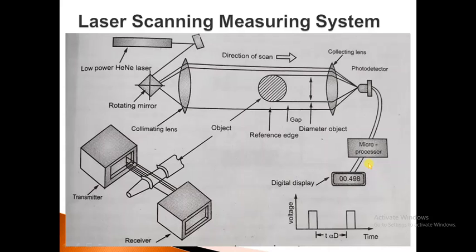Scanning laser beams can be applied in high production, online inspection, and gauging, and signals can be sent to production equipment to make adjustments in the process or activate a sortation device on the production line. The microprocessor measures the time interruption, relates it to the size of the object in the path of the laser beam, and converts from time to linear dimension.